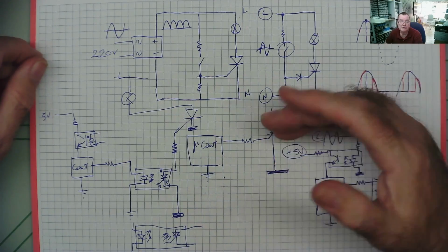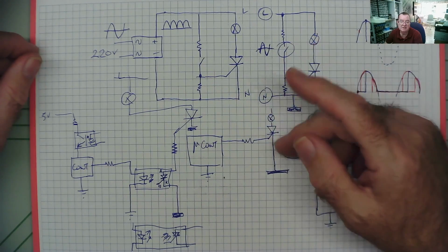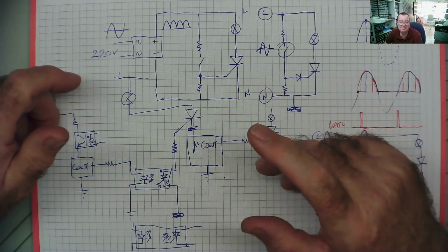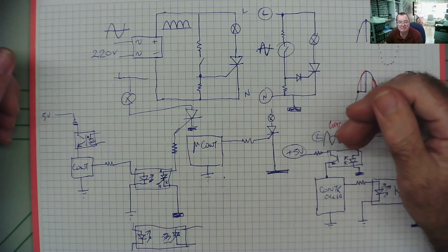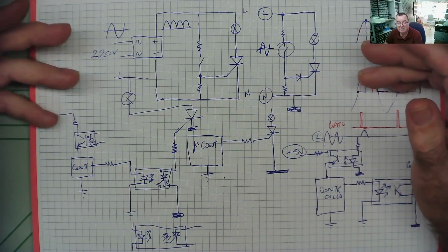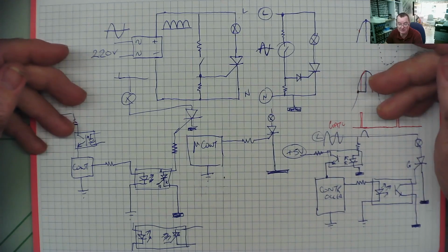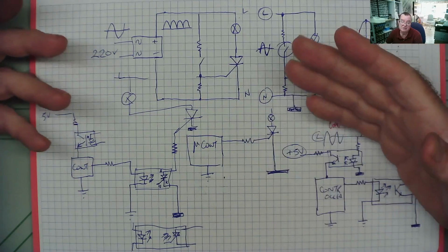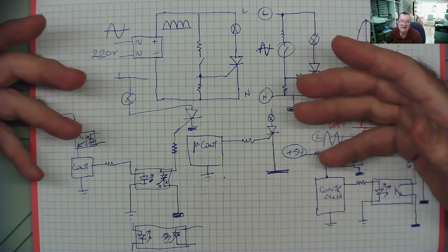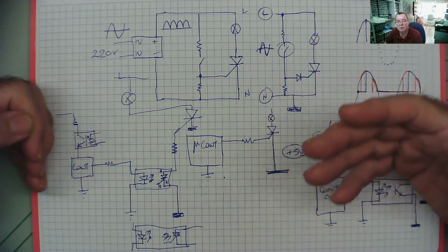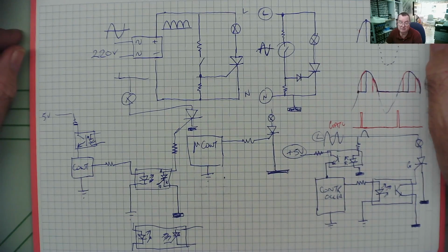You can usually also see that the thyristor is turning on with a voltmeter. So if you measure from the cathode to the gate, you'll probably see a little bit of a varying voltage. I won't show you on this video, but I will link the one where I was trying to repair those Christmas lights, where that PCB came from. And if you watch that through, you'll see exactly how it looks on a digital voltmeter on the volts range, and how I actually knew that the thyristors were switching. Okay, so that I will link at the end of this video and in the description.